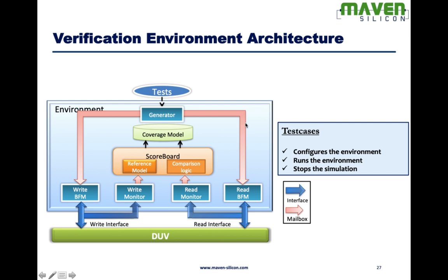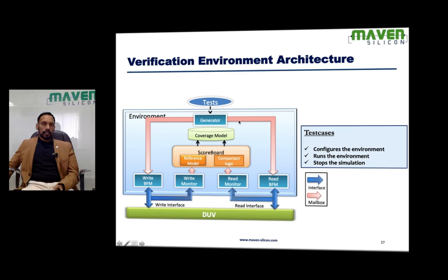Here, the environment has all the components: generator, all the drivers, monitors, and the monitors will be connected with the scoreboard, and the scoreboard will have all the components like reference model, comparison logic, and coverage model. So the environment is the top level component which instantiates the lower level components. We call this environment a reusable verification environment.